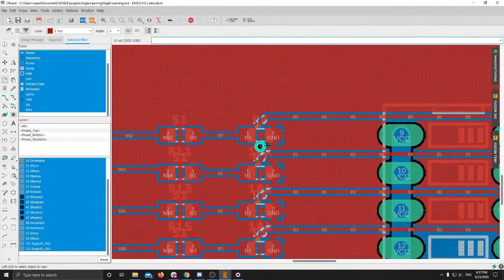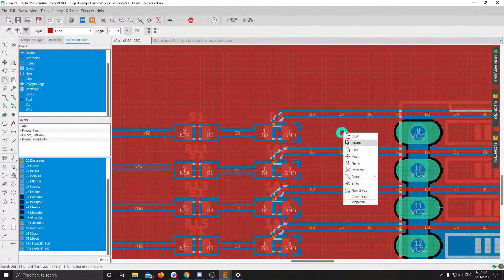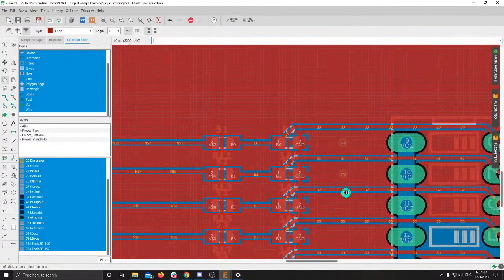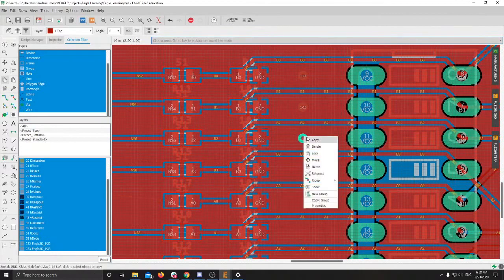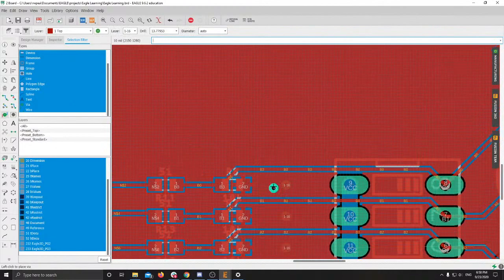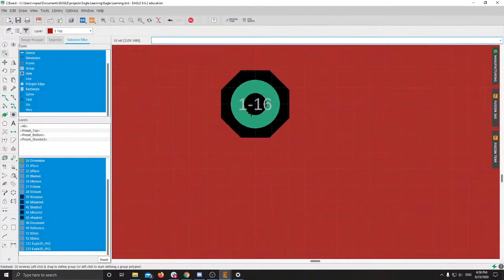So for instance, this looks like kind of a dicey connection here, so what I'm actually going to do is put one in each of these little gaps so that the better connected ground plane on the bottom layer can connect to it. And again, that's just specific to my design. You can place these all over, just make sure they're all named ground, otherwise they won't do anything. And you'll actually be able to see, if I place a random via here and don't name it ground and I do a rat's nest, it'll isolate around it.